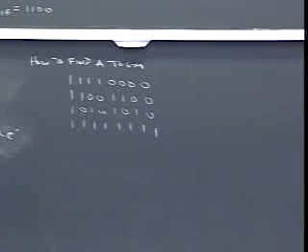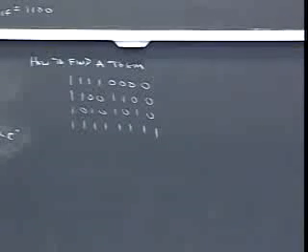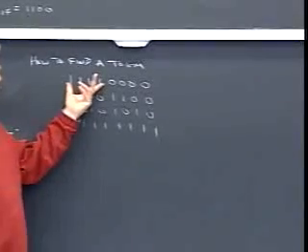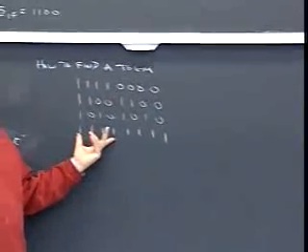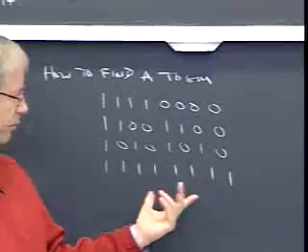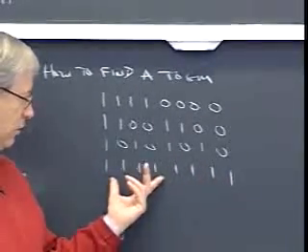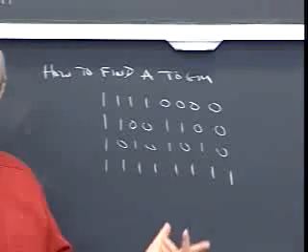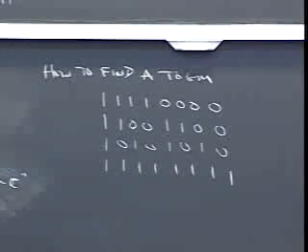So there is a generator matrix that's not in trellis-oriented form. In particular, by adding this to this, I can make this generator have shorter span. I can replace it by one which is 4 zeros and then 4 ones, which we've already found useful in constructing a trellis. All right?